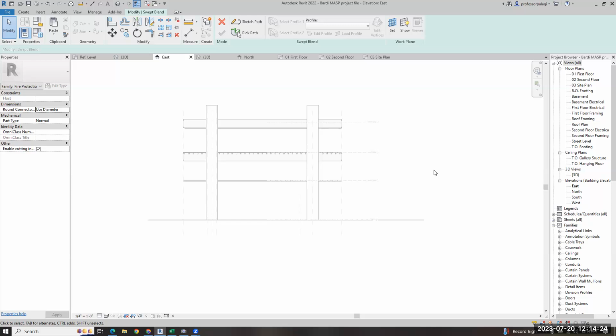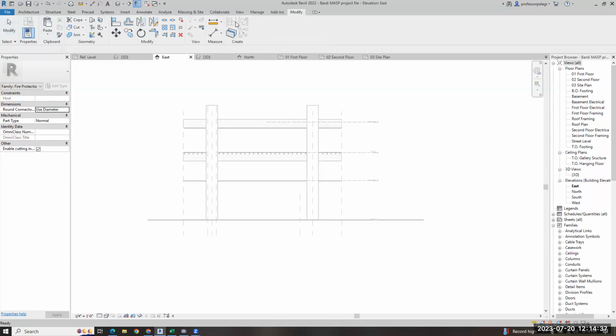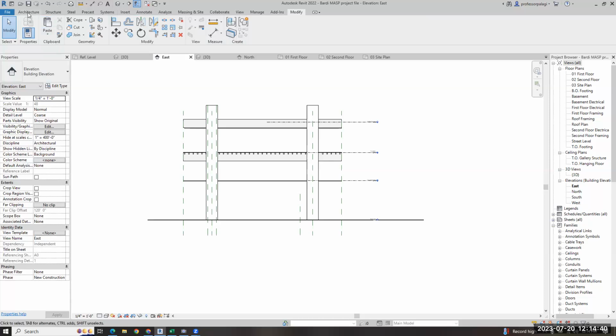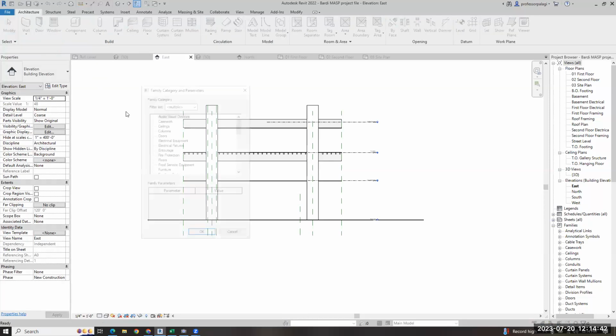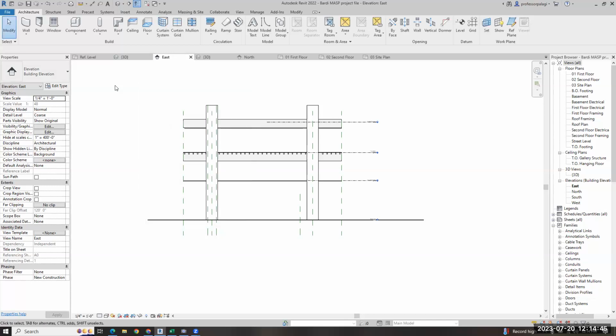This is actually just straight in project, but you would only be able to do it once here, and it's not a component that you can use again. So that's what I was showing. In a project, you can do model in place and do that. Those are the same tools that you get in generic model. I tend to like generic when it's super complex, like you want a crazy snaking form that changes and reacts, and you want to use it more than once. That's a nesting of a whole bunch of stuff.